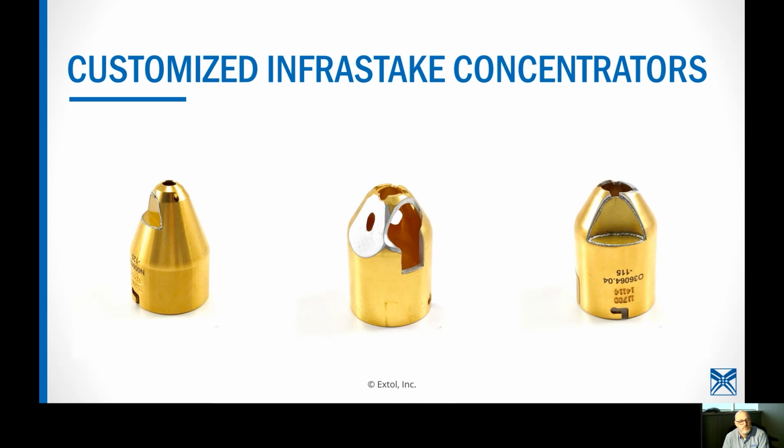Instead of that particular bulb, can you use an LED lamp? We have tried that, and yes, you can. We don't have it as part of the InfraStake offering because, quite frankly, the cost for LEDs was so much that it threw off everything. Keep in mind that the LED needs to have infrared output. The light that you can see isn't doing anything for you. You need the infrared part of it. You have to specifically buy an infrared LED, which is much more expensive than what we traditionally think of in the price of an LED.